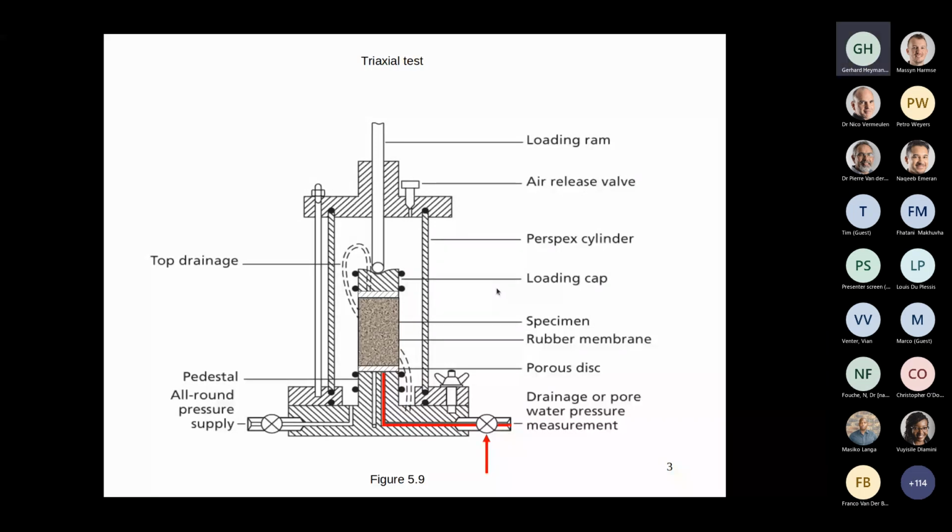Okay, so here's a triaxial specimen. There you can see it in the triaxial. And we fill the cell generally with water, and we can apply a pressure to this water, which of course will apply an all-round pressure to the specimen. Okay. Now, if you just differentiate between the consolidation stage and the shear stage, the easiest way to do that, if you're a young engineer and you walk into a triaxial laboratory and you're wondering, is the technician busy with a consolidation stage or a shear stage?